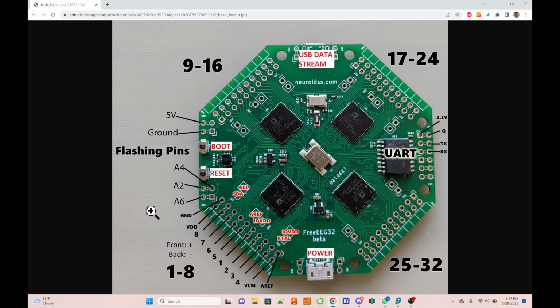usually goes on the earlobe, and most commonly, people use a system called linked ears. Suppose we have 32 channels distributed on the head according to the 10-20 system. Linked ears means that all of the negative terminals of all of the channels are connected together. And then 2 wires from there go to both the left and the right earlobe. And so the ears are linked. That's why it's called linked ears.